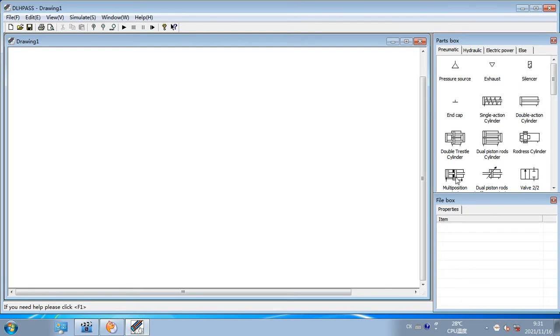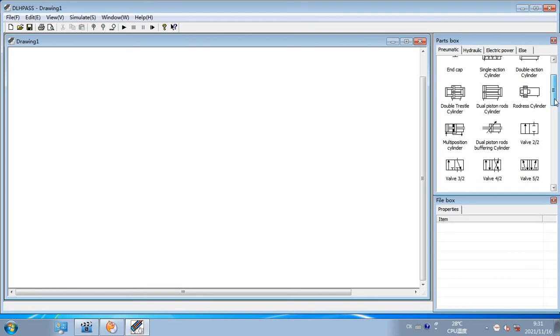And we've got the multi-position cylinder, which you can see right here. A piston is attached to the end of this piston right here. So these two pistons are attached to each other, and this is the inlet port, and you can see it's connected to the area of the second cylinder. So they both extend at the same time and retract at the same time with a greater force.